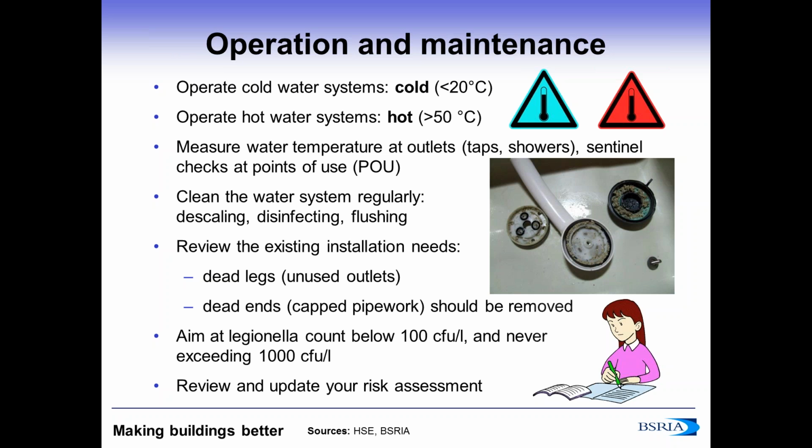You could ensure that the cleaning of the water system is performed thoroughly, going as far as dismantling shower heads to clean and descale them. Also do a regular tour of the building. Check whether some taps and showers are still accessible or used, and if some pipe has been disconnected for some unknown period of time, you might identify an opportunity to remove them.